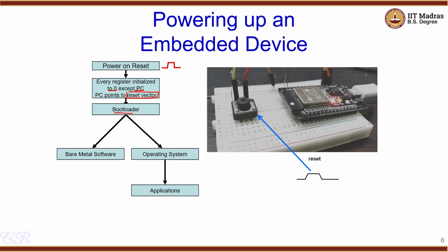If it's your regular PC, you would still have something like a bootloader, but after the bootloader, you would have another step known as the BIOS, which performs a lot of initializations of memory and different peripherals, tries to identify what is connected in your device, and also does some security checks to identify what kind of software is present, whether the operating system that you're executing is a valid operating system and has not been tampered with. Finally, the BIOS would load the operating system. But to keep things simple, we are just going to follow this particular process.